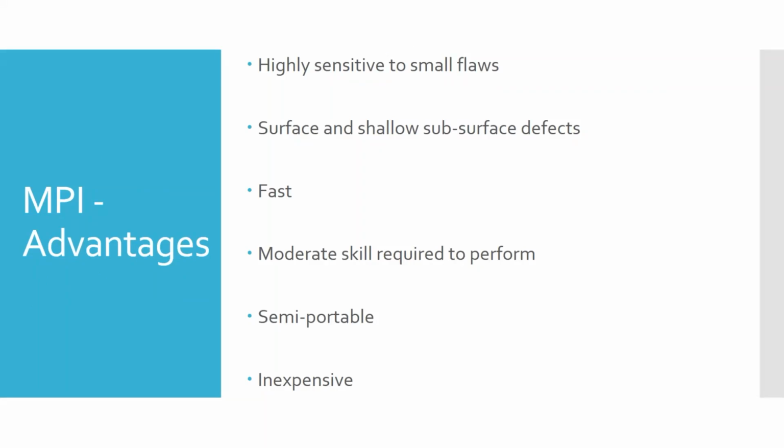It's a very quick method. When we do it, you'll see it really doesn't take that long to perform. The longest part of the whole thing is the inspection after you perform the method. You apply the magnetic particles, and then you have to inspect to see. That one's pretty obvious. Some things, the indications are much, much smaller than that.